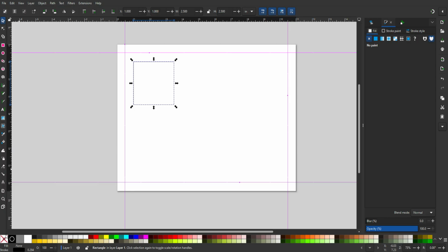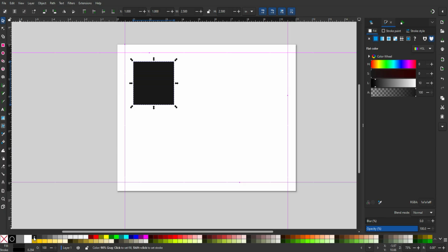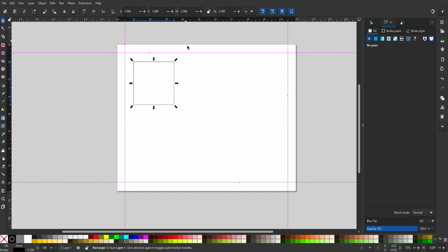And for that, the laser is going to be set at a lower power so that it's just burning, etching. So for any of your cut objects, you want to have no fill. And there will also, we'll get into that in a second, but for an etch object, for something you're going to etch, you'll have a fill typically. So if you wanted to etch just a square into your material, you'd have it filled. But we're going to get rid of our fill for right now.